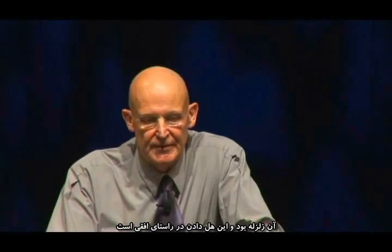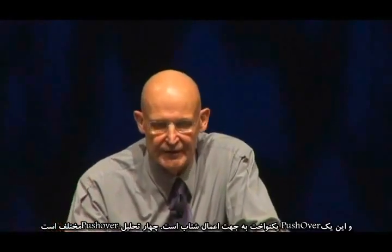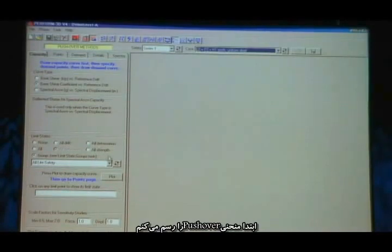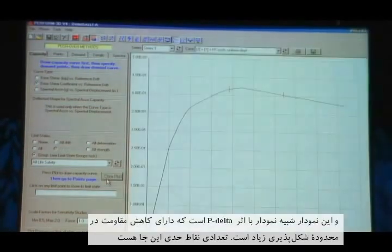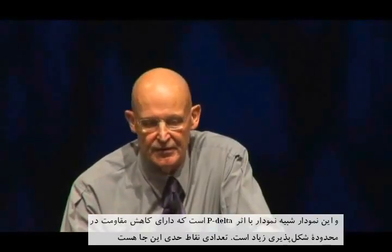That was earthquakes. And this is now, it's going to be horizontal, the push in the horizontal one direction, and it's a uniform pushover, and there are 4 different pushover analyses here. I'll just look at one of them. And I'm going to, first of all, plot the pushover curve. And this is what it looks like. And there's some P delta effect, so there's some strength loss as it gets into the buckling range.